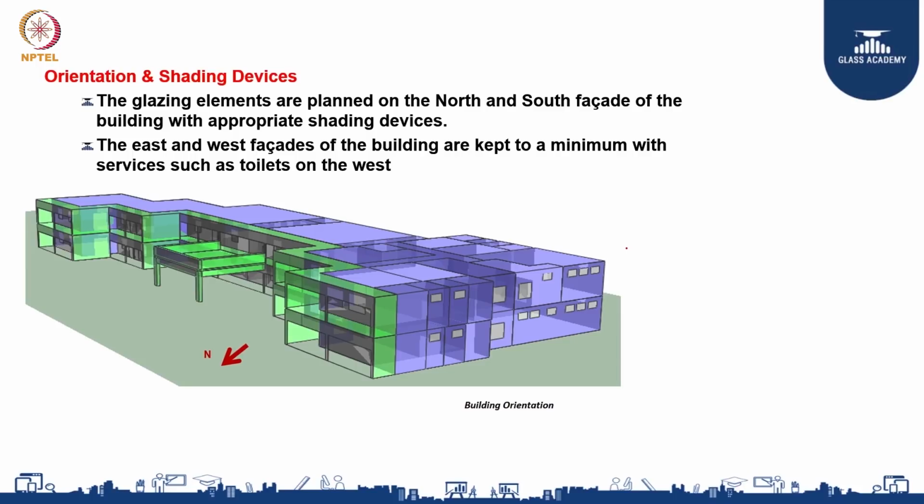Then you add these parameters into your design model and see. If I do use roof insulation, let us say costing me 5 lakhs, my energy savings is 1%. But let us say I do shading devices costing say 7-8 lakhs, and my energy savings is to the tune of 16%. Then you would rather spend that money on shading devices than roof insulation. These are things we can play around with at the design stage to achieve the best optimal solution.